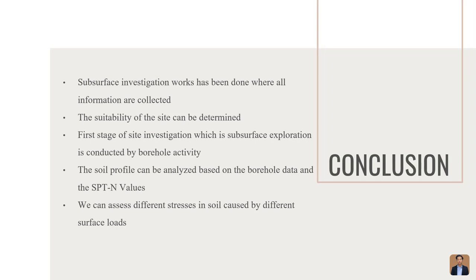The soil profile was analyzed based on the borehole data and the SPTN values, which show the type of soil and the height of the soil. Finally, we can assess different stresses in soil caused by different surface loads. Therefore, we are able to justify the suitability of the soil for the proposed project.